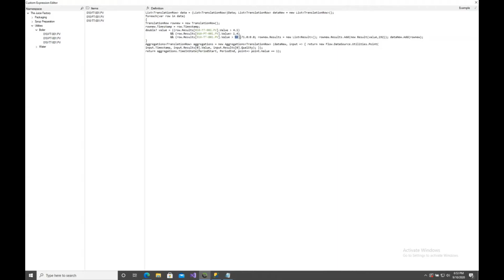If it matches all of those 3 parameters, then return a 1, else return 0. So what am I doing? I'm actually taking my analog process variables and converting them to a discrete tag, a 1 and a 0. If it conforms to all 3 of these conditions, return 1. If it doesn't conform, return 0. So I've got a discrete representation of my process parameter limits.